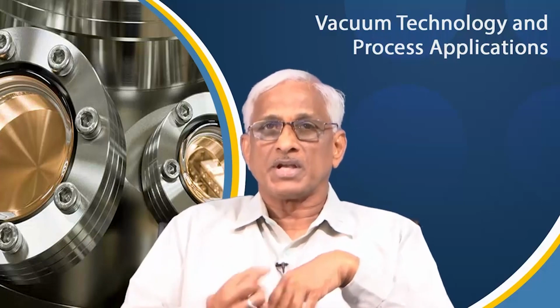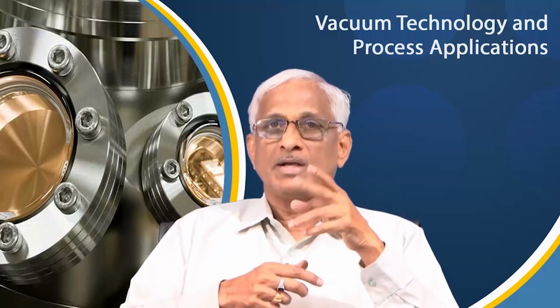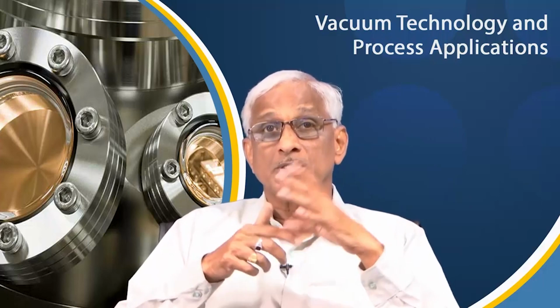For chemical, pharmaceutical, force applications, filtrations, for example, in a chemical industry to accelerate the speed of filtration, if you try to put vacuum on the receptacle side, then the filtration speed will increase. I did not tell this in the last class, but that is also one application, and it is going to save an enormous amount of time in process industries, in chemical and pharmaceutical industries. Instead of 5 hours filtration, it may be 1 hour, then it saves a lot of money, and that saving compared to the vacuum technology cost of a rotary pump or something, it is hardly anything.